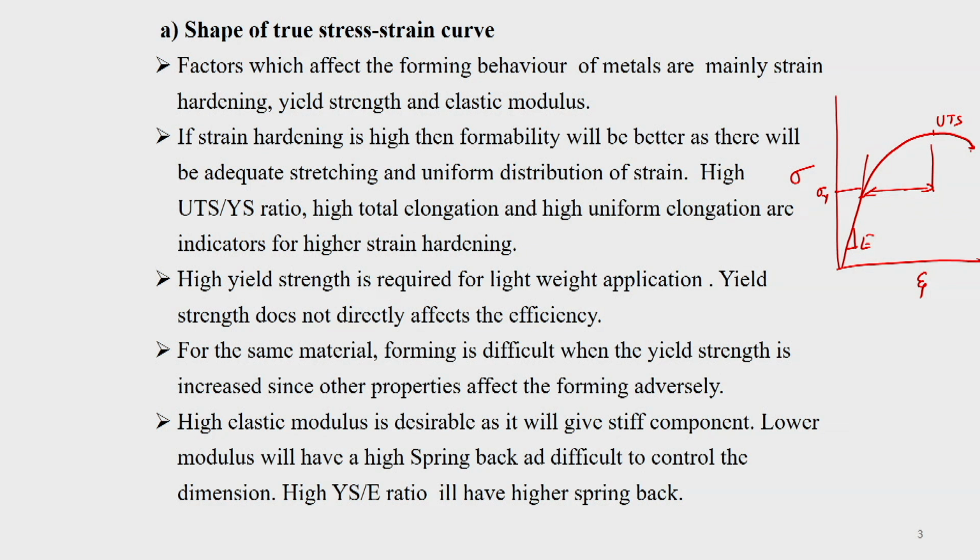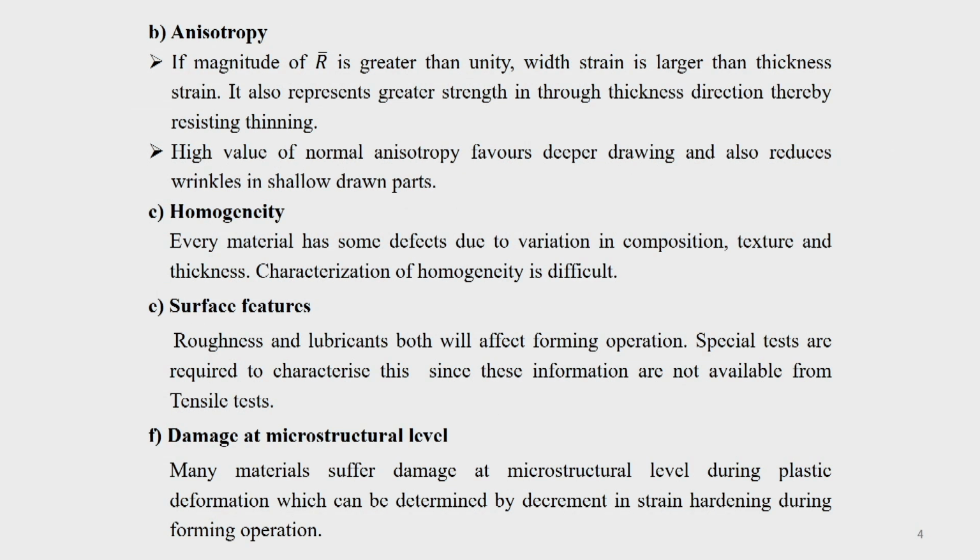properly. And another is that a high yield strength to Young's modulus value ratio will have higher spring back. That is also something people have found experimentally, that those materials having a high yield strength to Young's modulus value ratio have a higher spring back effect.